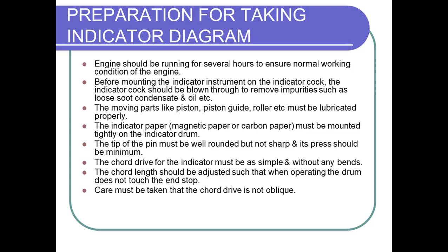There should not be, the sea has to be calm, and you go to the speed. Sometimes we may not go to the MCR speed altogether, but depending on the chief engineer and captain's discretion, they come to a maximum RPM whatever they want. So now we are blowing through the indicator cock, because there must be soot deposit over a period of time, because combustion is taking place inside, and then there will be some soot deposit, so we want to remove it, so we just blow through.